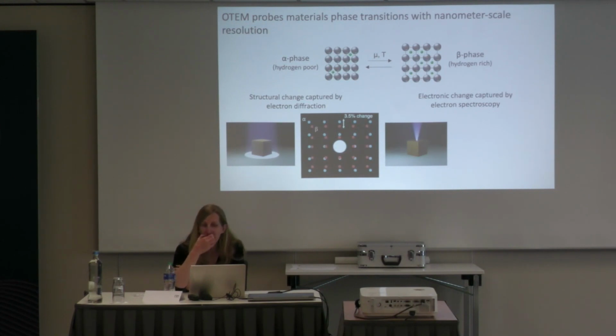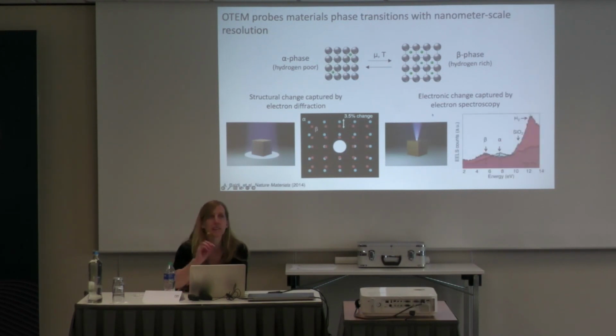So the main structural change, and you'll get to see some videos of this too, is just that lattice expansion. There's not a structural phase change apart from the lattice expansion. It's not like you're going from FCC to BCC or some other weird phase. Yeah, great question. And then in addition to looking at diffraction, we can also look at spectroscopy.